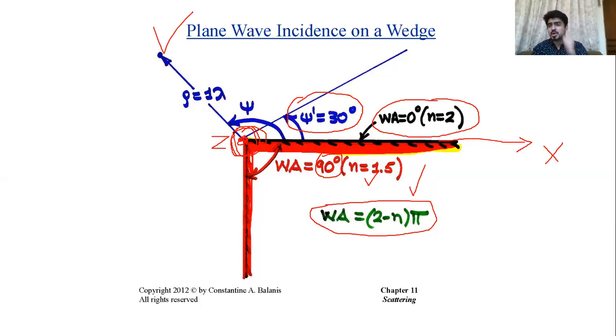And since for the electrical line source, your E field is along the z axis, parallel to the z axis, your H field is in the xy plane, and as a result your H field is perpendicular or transverse to the z axis. So we can call this polarization TM to Z polarization. This TM to Z polarization is also nothing but a soft polarization, and that is given by this electrical line source. It is generated by the electrical line source in the far field.